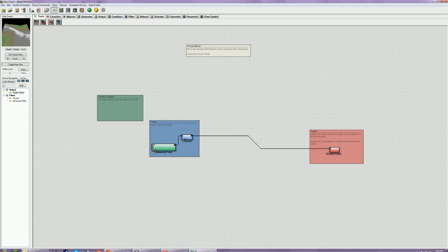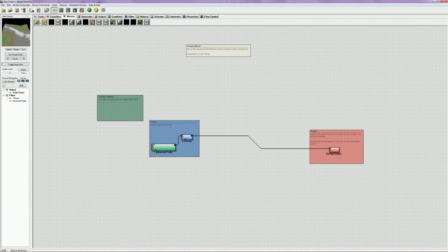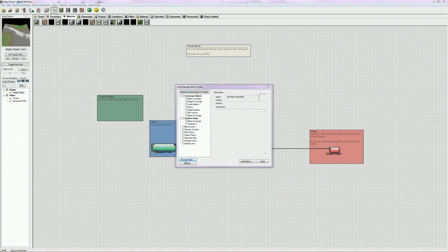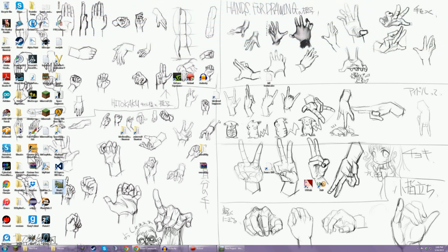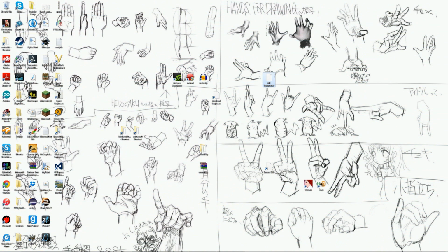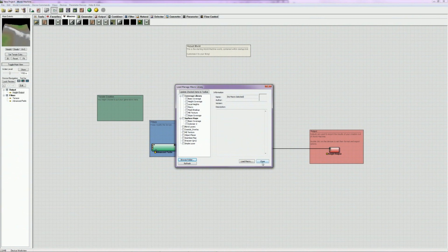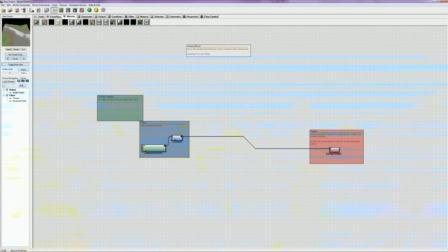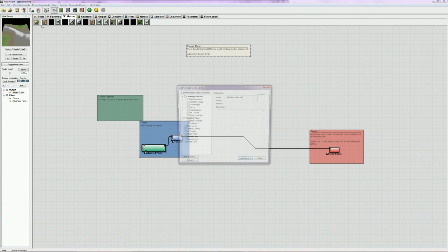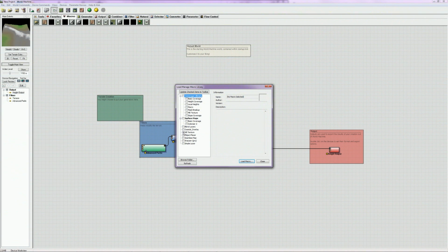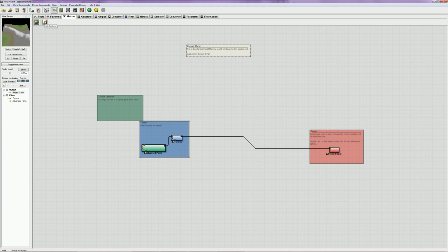Okay, so import the macro. You go to the Macros tab, open up the folder, browse folder, and then you take the macro and place it anywhere in this folder. But I already have it. And then you're going to have to open this up and check that and update checked items toolbar, and you'll have ME texture. Drag this here. Not much you can do with it now because you need 4 inputs.